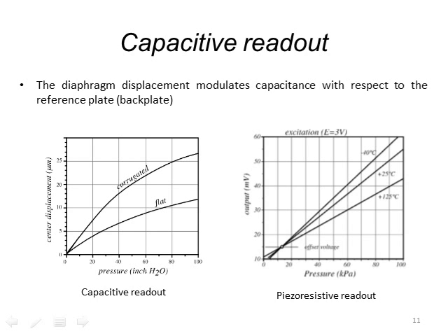So the capacitive is easier to integrate on chip, and the processing of this is easier, but you have a nonlinear readout. Indeed, you can do calibration to compensate for this. Most of the modern highly integrated pressure sensors are made from these capacitors, but still a large number are made from this old technology using piezoresistive, because it's a pretty reliable technology.